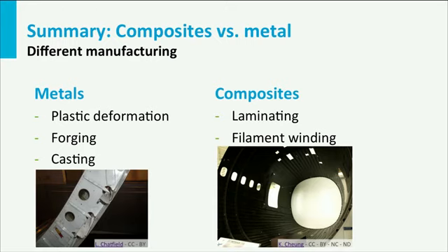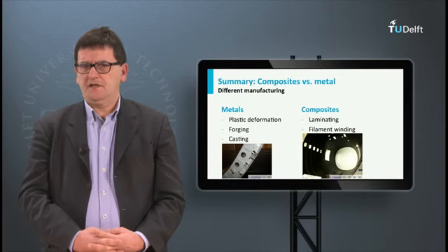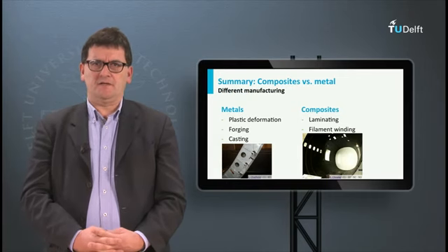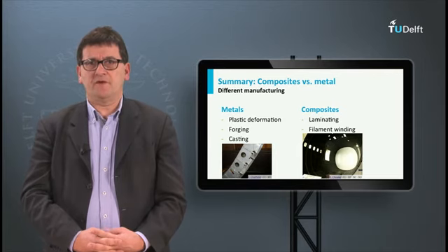The composite structure on the right-hand side is a much more integrated structure. Local thickness variations are made in one autoclave cycle. The reinforcing stiffeners are bonded in a second cure cycle. These stiffening skins can be made by laminating, or the skins can be made by filament winding.